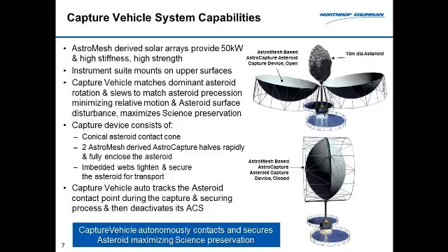The device closes and locks, and then cinching cables snug it tight. You turn off the ACS system and let whatever happen. Once you verify it from the ground, you activate it again, and for a very small fraction of your propellant load, you can completely despin the system.